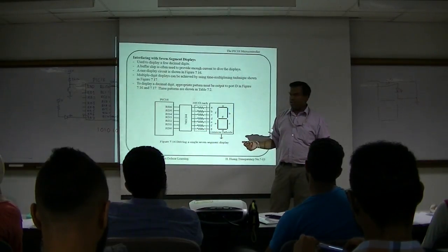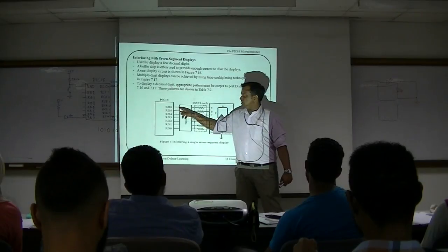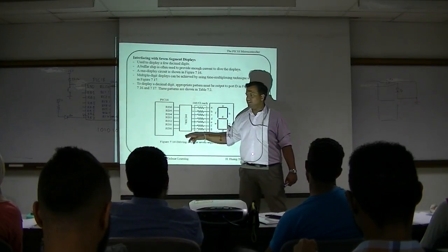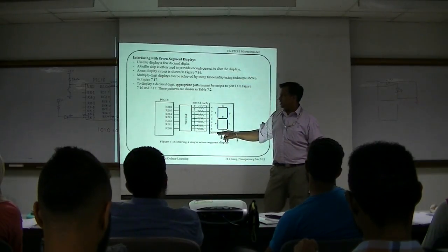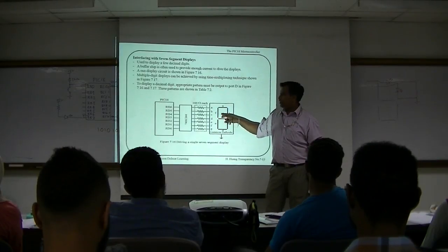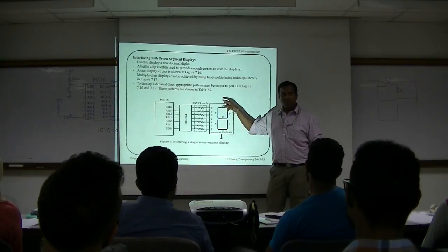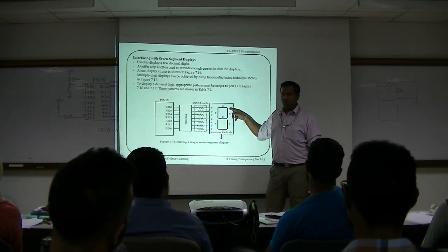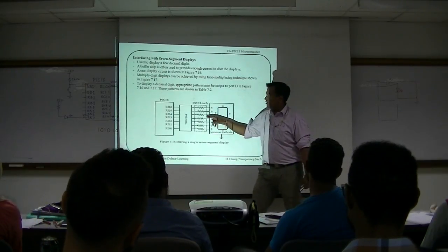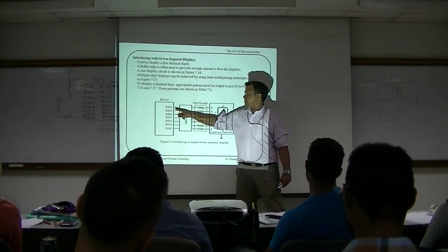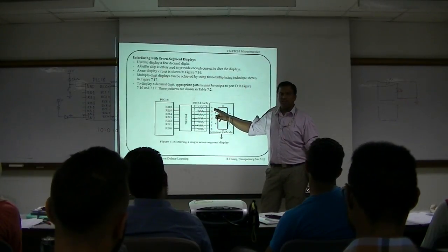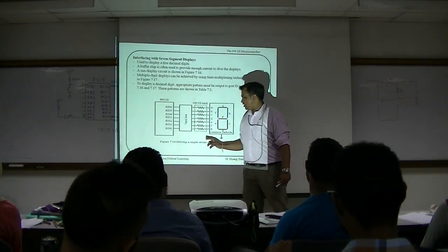Now this 74HC244 is actually a buffer IC. It increases the current. So you connect each pin to the IC and the IC connects it to each segment. Always you have the sequence A, B, C, D, E, F, G. Simple. Go one round and then middle. So you know the sequence. Let's say for example pin number 6 is connected to A and 0 is connected to G.